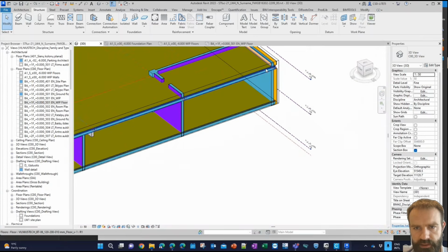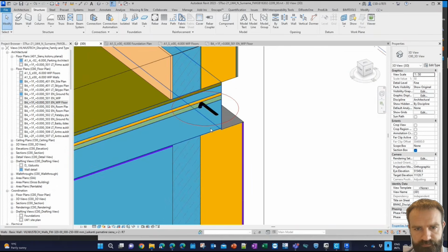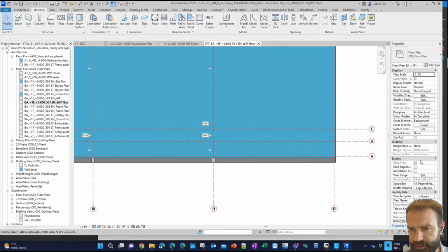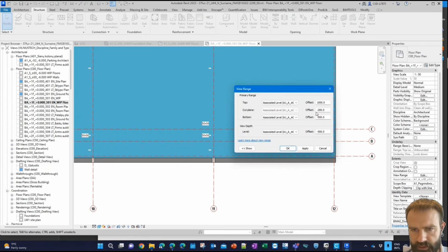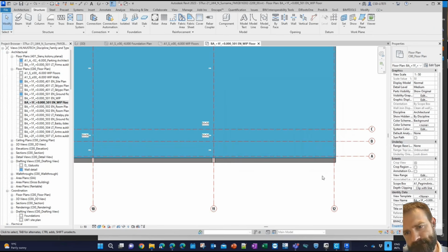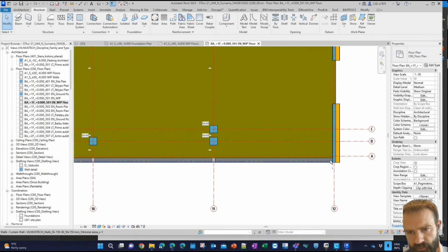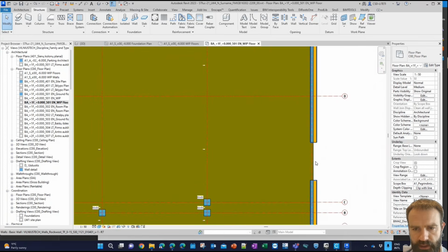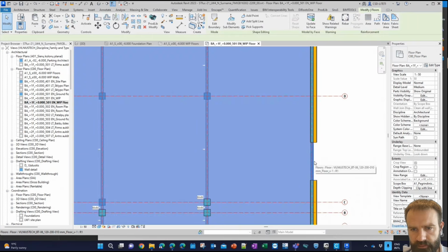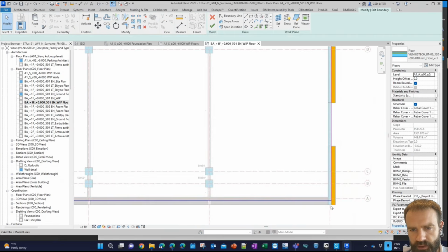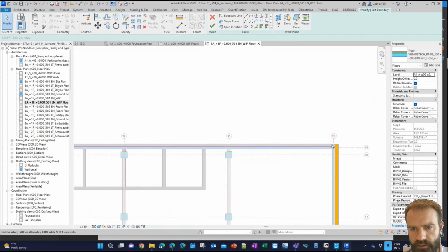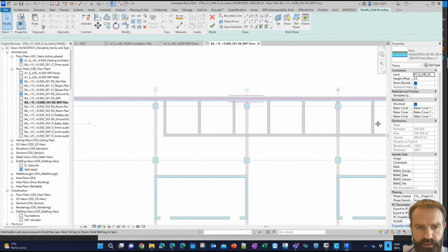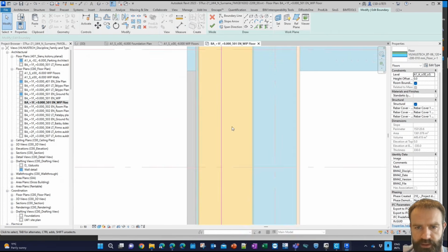Okay, so it means my walls were moved completely down. So in this case, I will use the opposite and move here, let's say 50. Okay, so now I see my wall construction, and I can select the floor, double tap on the floor, and on this side is okay, on this side is not okay.